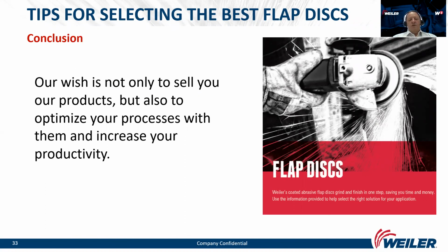when you grind with zirconia alumina flap discs, you have to push a lot to achieve the self-sharpening effect of grains. But with ceramic flap discs, you should not apply too much pressure. And that is quite a tough job to achieve during grinding.